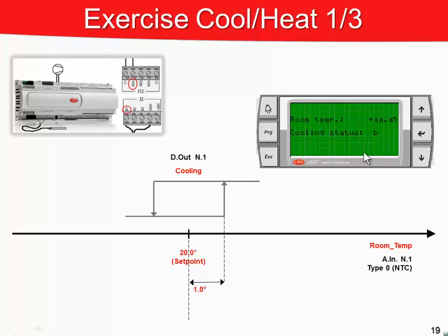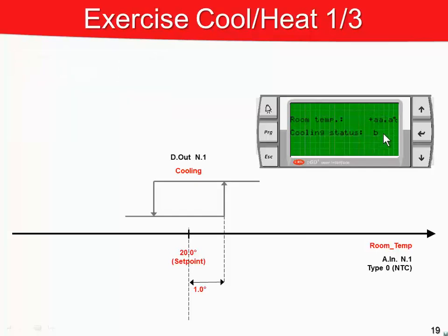Regarding the user interface, I will use a terminal using the display PGD1, which has 8 rows by 22 columns. I will show 2 fixed texts describing what there is beside, and here on the right I will show the value of temperature and the cooling status.